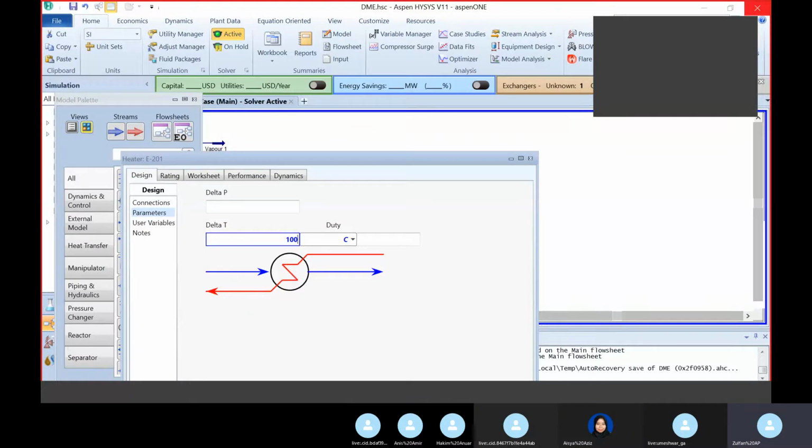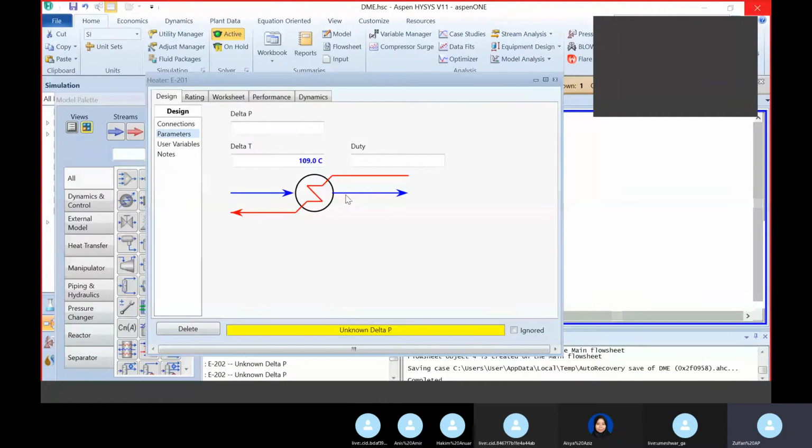That's the steam, yeah. But okay, fine. It's something that we don't know. We also don't know what the pressure level of the steam is. If we don't know the pressure level of the steam, that means we don't know at which temperature it condenses. That means we don't know what the enthalpy is that is going to be given to the stream. So if we don't know the enthalpy, we cannot calculate what the flow rate is.